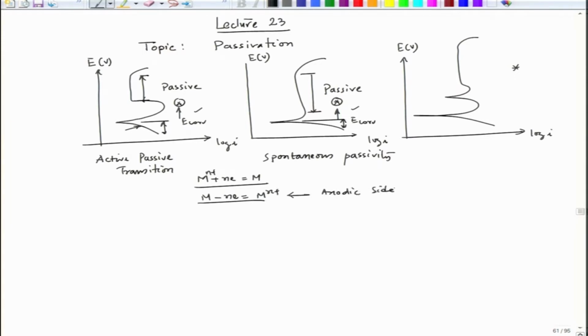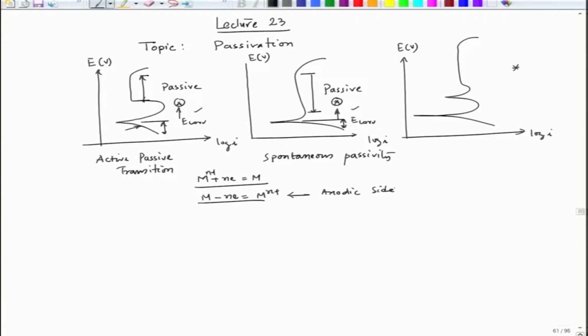We also defined passivity as basically chemical inertness introduced into the metal when that metal is exposed to an environment due to its ennoblement or anodic polarization. There could be other instances like lead, where ennoblement or passivation appears because of lead sulphate formation in H2SO4. So, those cases we have considered.